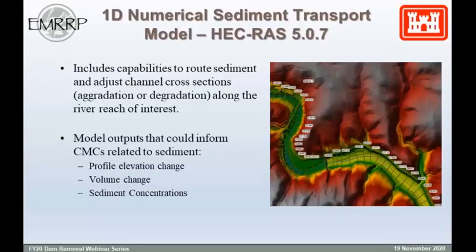Some of the model outputs that could be used to inform common management concerns related to sediment are the profile elevation change. Basically, when you have a 1D HEC-RAS hydraulic model, you need to define your geometry. And when you only do hydraulics, that profile is going to be fixed. It's not going to change no matter what flow you're running through the model.